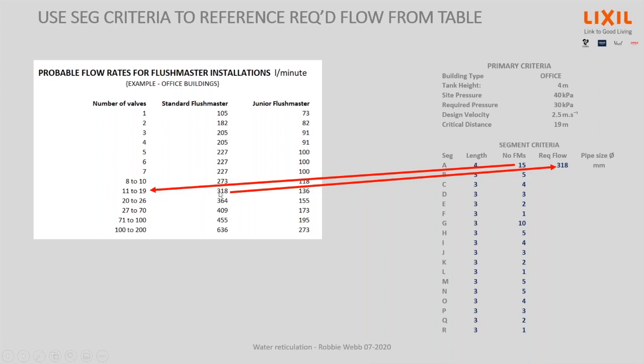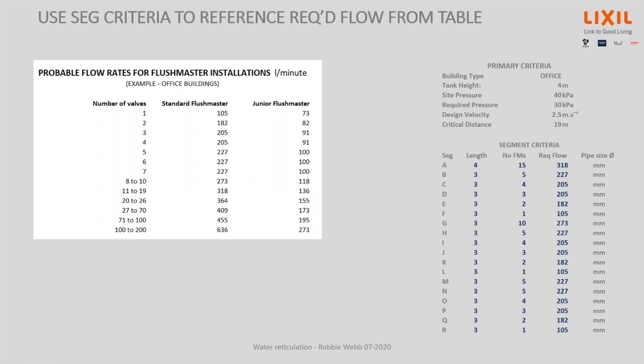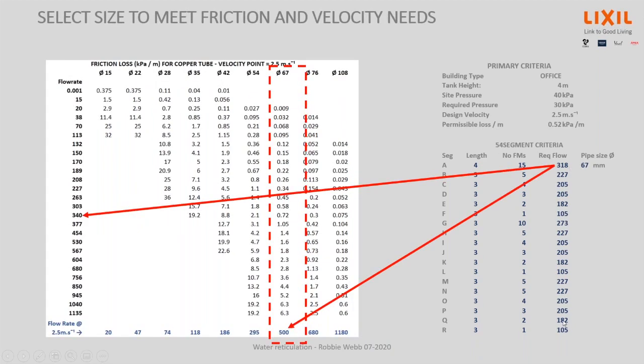Okay, so that's the band which is going to give us that friction loss, and down at the bottom, or less than that friction loss. At that rate, it's actually a little bit more, but we're not going to go to a 3-inch pipe. And then we're going to check at that velocity, we can deliver 500 liters per minute. We only need 300, so we're safely covered. Okay, do the same thing for each and every segment.